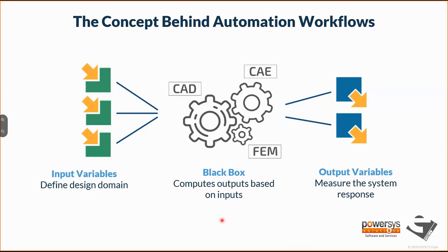All your CAD processes, CAE processes, or an FEA, CFD process, can all be treated as a black box wherein you can feed in input variables that are free parameters and expect responses from that black box as a measure of the system. Once this is well defined, you can then define your input variables and your response variables that help you define your targets and objectives.